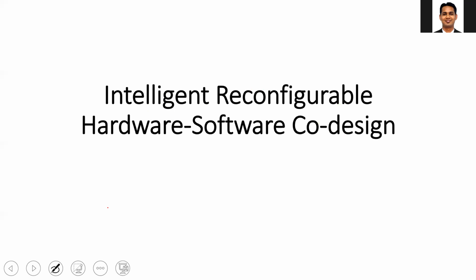As we have discussed, we are talking about the heterogeneous system on chip, where you have different types of components. For example, you have sequential processors, and you may have co-processors like DSP, SIMD, that is single instruction multiple data, and a floating point unit coprocessor. You may have ASIC, you may have FPGA. Once you have your algorithm, deciding which part of the algorithm is to be implemented where is called hardware software co-design.